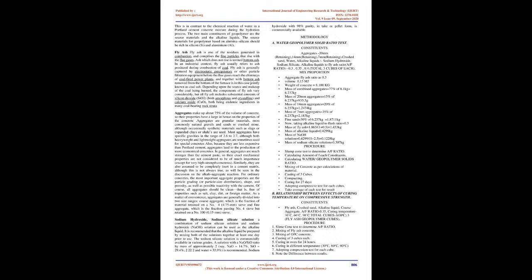The old rule of thumb for water quality is, if you can drink it, you can use it in concrete. Although good quality concrete can be made with water that is not really potable. Indeed, more bad concrete is made by using too much drinkable water than by using the right amount.